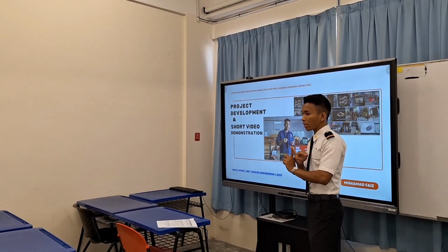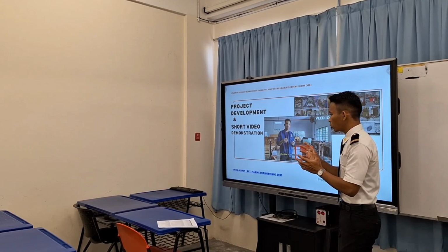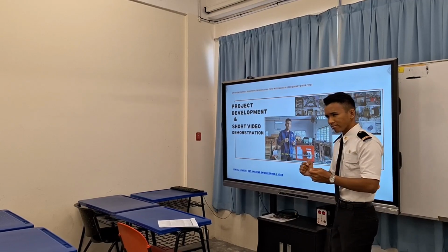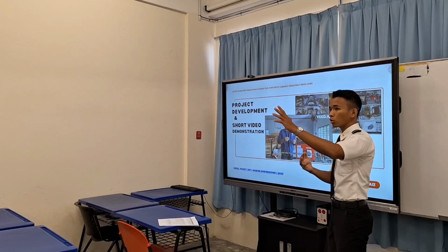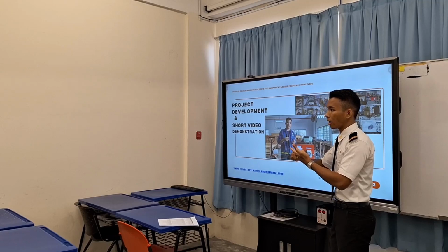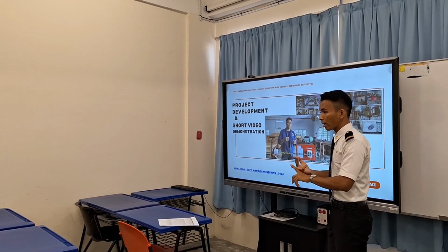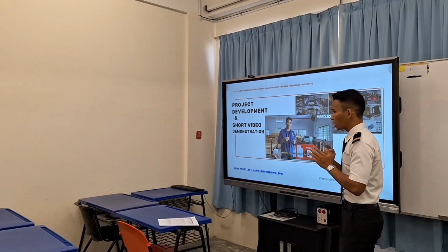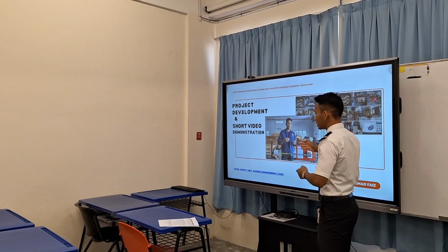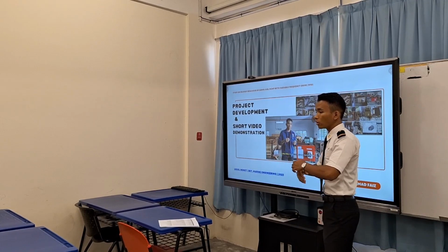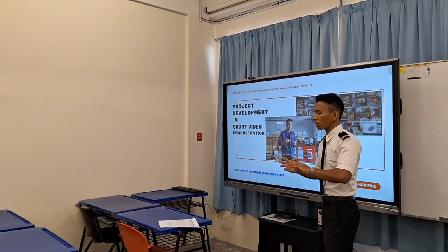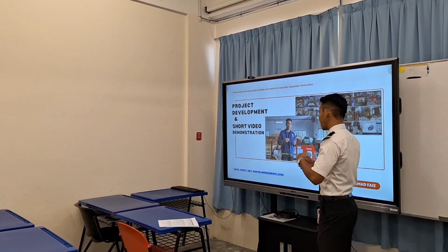And the third one is the dimmer. The dimmer works on the intensity of the voltage, like a dimmer controlling the intensity of light. You change the potentiometer, because they restrict the voltage by the capacitor and so on. But it is not applicable in real-life work, because the dimmer will cause the motor windings, the stator, to overheat in the long term, and this is really not recommended based on my research.